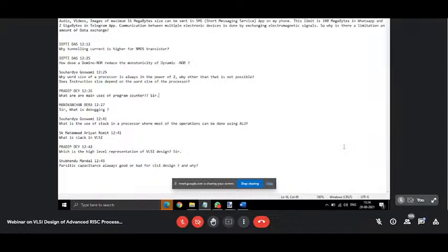0. Yes, the AND gate output is 0. That is wrong, in fact. Apparently, X and X bar gives 0, but in practice, it is not that. Let's say your input is going from 0 to 1, a pulse. When it was 0, X was 0 and X bar was 1. When X has gone to 1, X bar is yet to go to 0 because of the timing delay of the NOT gate. So for a small time, both the inputs are 1.